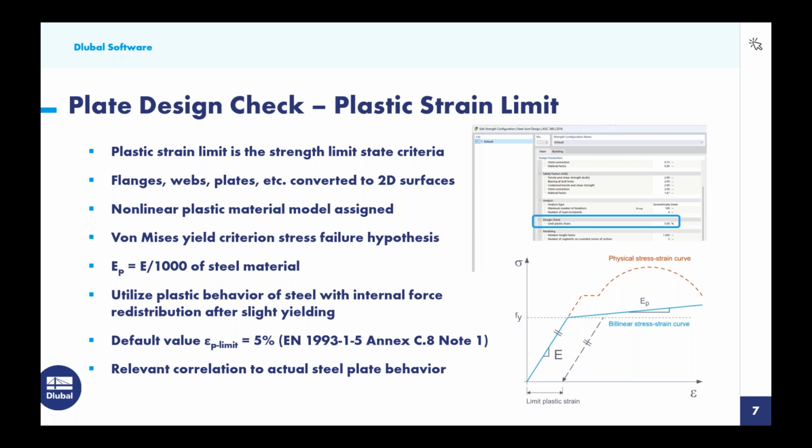Now, a big question is, why are we setting the limit plastic strain instead of the yield strength in terms of the yield stresses? The reason is we're going to have hundreds, maybe thousands of FE mesh points on these submodels. And when a single FE mesh point reaches this yield strength, Fy, then inevitably we would be saying that the entire connection is failing,